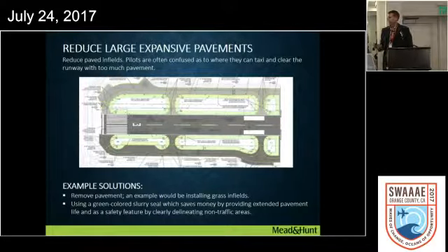What we have found to be more beneficial is a green slurry seal treatment. One of the concerns with the green paint is that it fades fairly quickly due to the low color of the pigment. Whereas a slurry seal is homogeneous and a quarter inch thick. As it continues to wear, you have a pretty good wearing surface there, and it does minimize the ongoing maintenance for the airport staff.